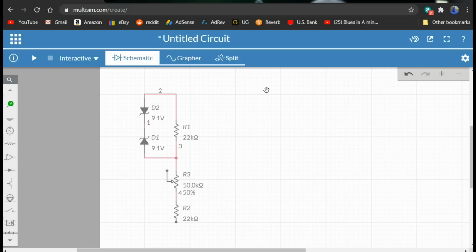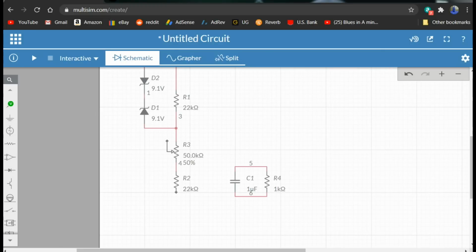So for the op amp, I forget what I'm using. Hold on a second. Yeah, we're going to go with an LM741 or an equivalent, whatever we have. The part that I just drew there is going to be our RC timing circuit that is going to determine our frequency, and that's what we looked at in that little title I showed you.